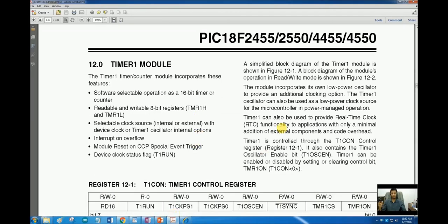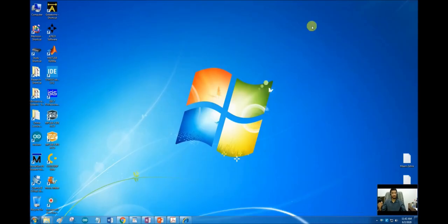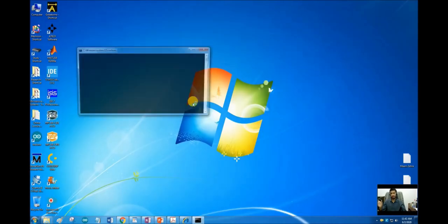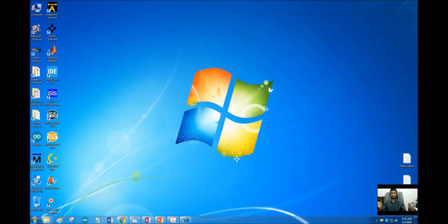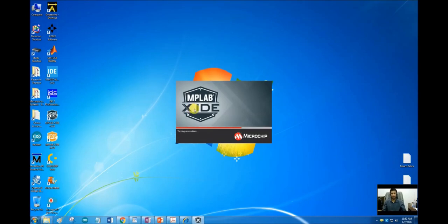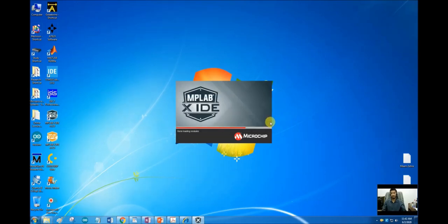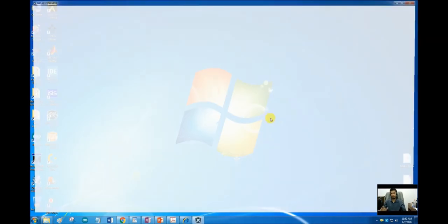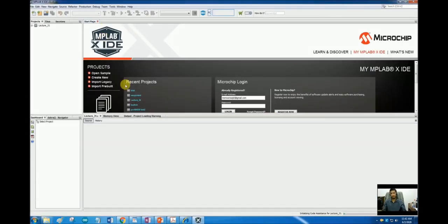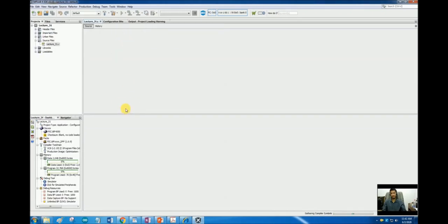In the previous lecture, we were using polling of the TMR0IF flag using a while loop, while not TMR0IF. Let me open the code, and we will see that we were manually checking that flag, the timer overflow flag. We were not using interrupt for the timer. We have studied interrupts, but we have only used interrupt for the external interrupt source up till now. So before moving on to timer 1, I would like to use interrupt for timer 0 as well.